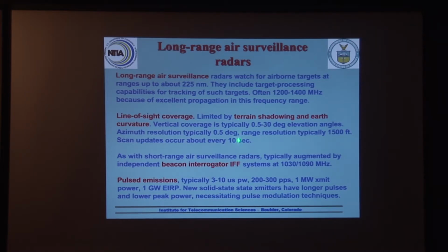So the scan updates for long-range radar are every 10 seconds, whereas for short-range radar, they're every 5 seconds. So if it's a tactical situation, that could be a bit of a problem, but that's the trade-off you face if you're going to work out to longer ranges. Again, it's important that these radars typically be augmented with beacon interrogator IFF systems for all the cooperative targets in